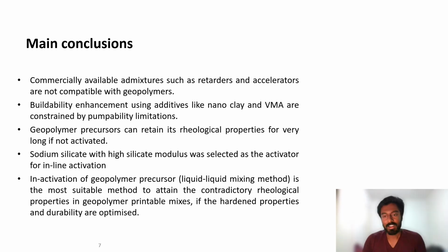Geopolymer precursors, unlike cement, when added with water, don't react. Cement, when you add water, the time starts ticking because the hydration process starts to take place. But geopolymer precursor doesn't happen like that. You need to activate using the activated solution. So we can have a strategy called inline activation, where the precursors can mix with water, and that slurry will have a really long open time because nothing happens for that mix, chemically at least.